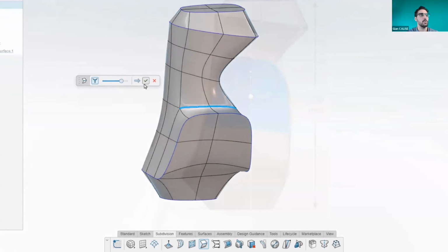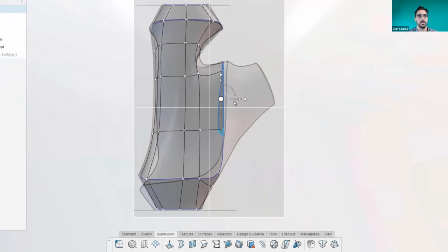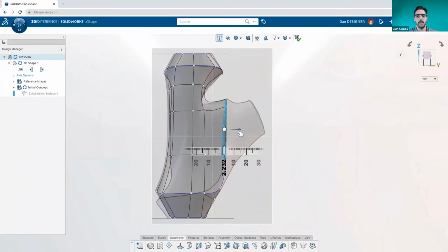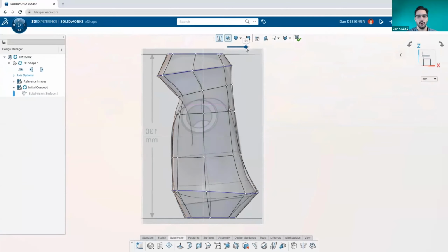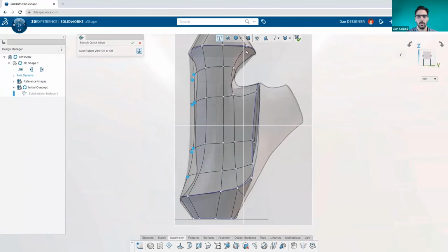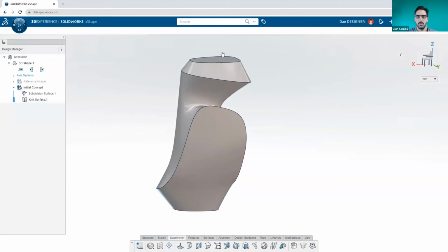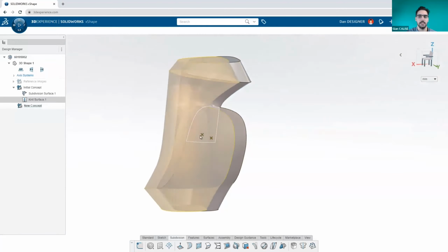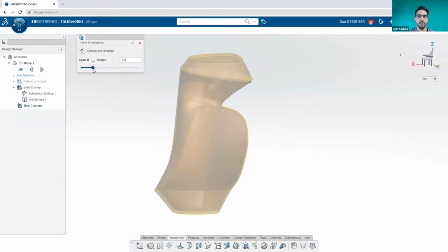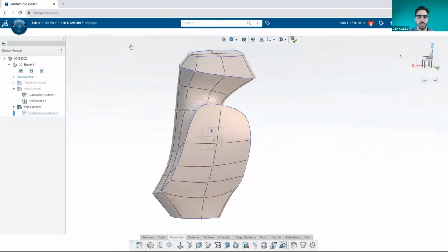And you can adjust the smoothness and severity of those creases. When you're modeling from 2D sketches, jumping back and forth between orthographic views from one profile to another makes it a lot easier to sculpt the shape that you're looking for. All right, so we can copy and paste previous surfaces to explore new concepts and scale them if we need to, and then just continue sculpting.